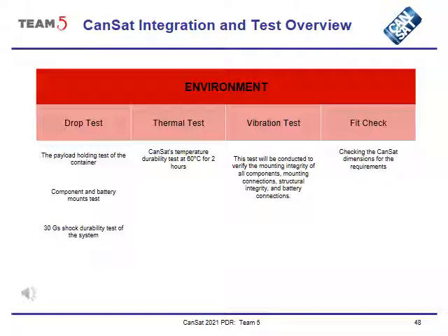Thermal test. Cansat's temperature durability test at 60 degrees Celsius for 2 hours. Vibration test. This test will be conducted to verify the mounting integrity of all components, mounting connections, structural integrity, and battery connections. Fit check. Checking the Cansat dimensions for the requirements.